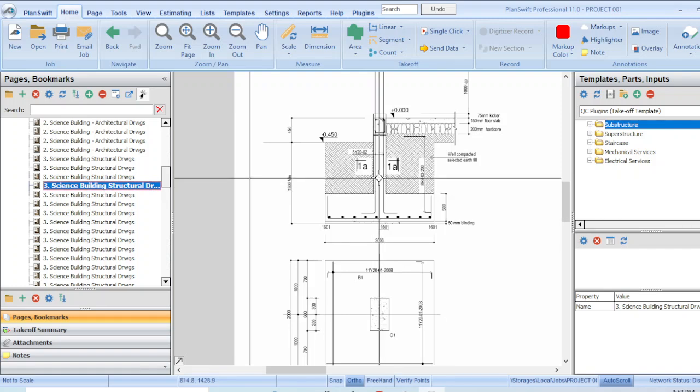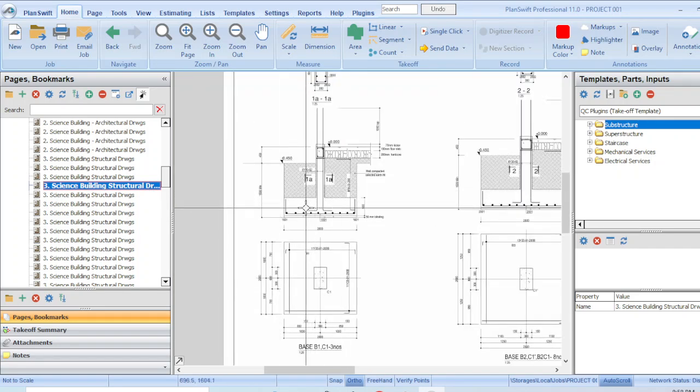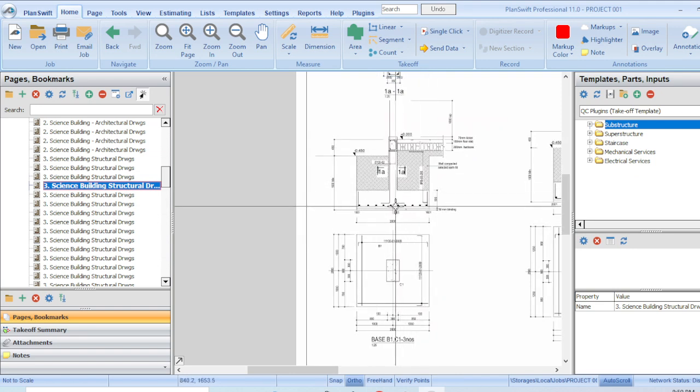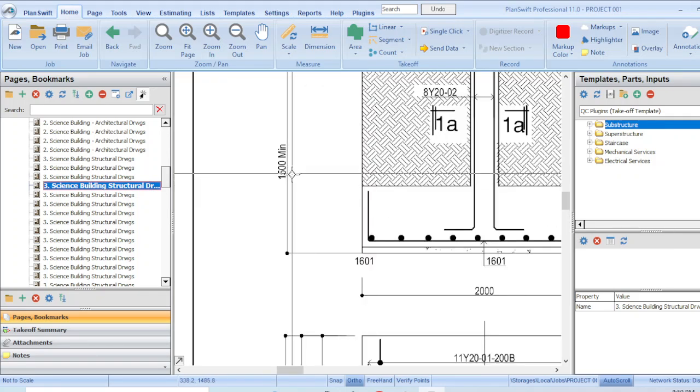You know, underground works like excavation, when we are doing measurements for excavation works, all the quantities that we establish are provisional. They have to be confirmed on site. That's why we do the measurement on site after excavation. But the quantities we provide in the BOQ are provisional quantities, because underground works have a lot of uncertainties, right? Okay, so our depth is 1.5 minimum. We are going to use this as our depth.